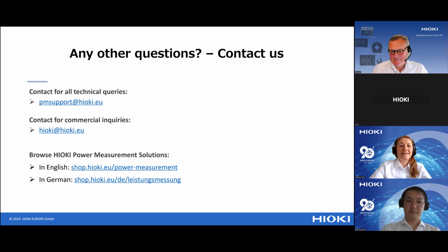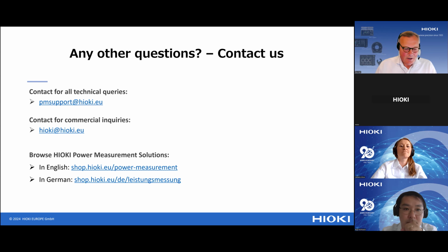The next question: does the same philosophy related to the onboard charger and power analyzer selection apply to off-board DC fast chargers, even if we are not the developer of the power modules, but look at the unit as a complete system for overall evaluation? For overall evaluation of chargers, it depends on what kind of signals you want to measure. If you have a fast charger connected to the grid with a DC output, then it's not essential that you have a very high bandwidth.